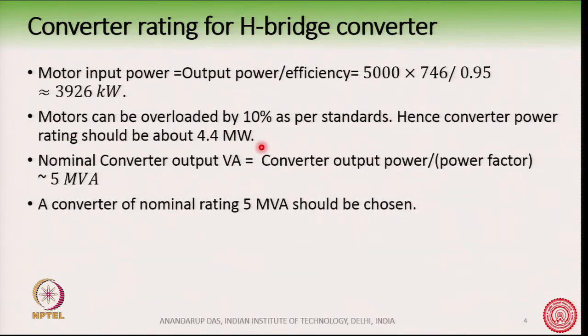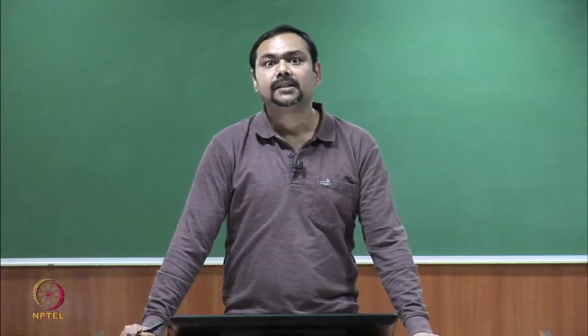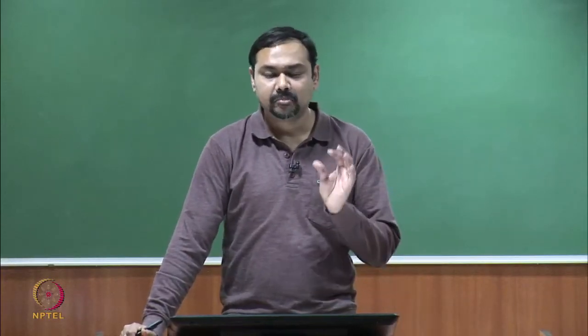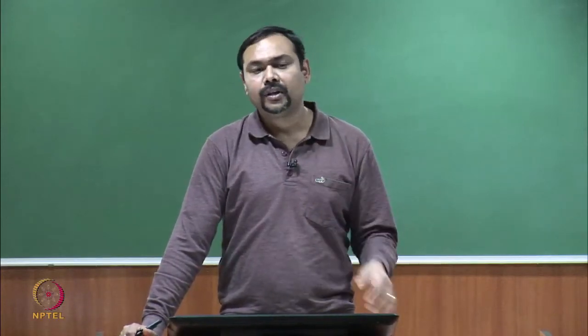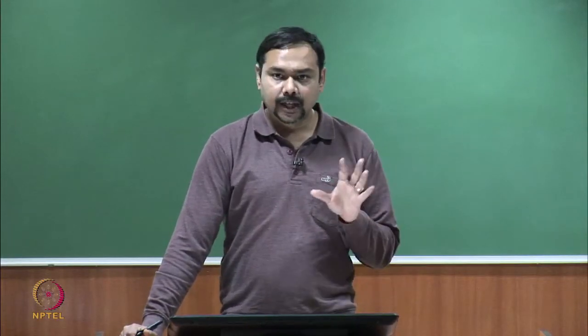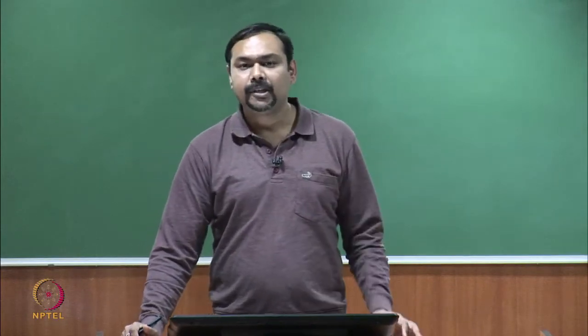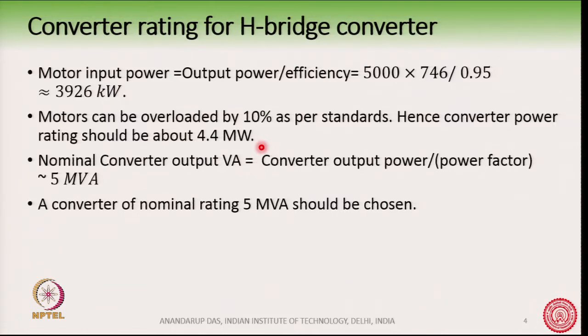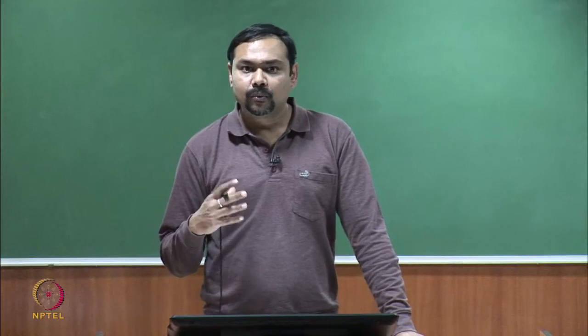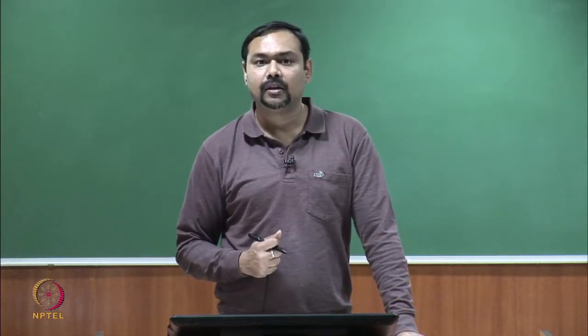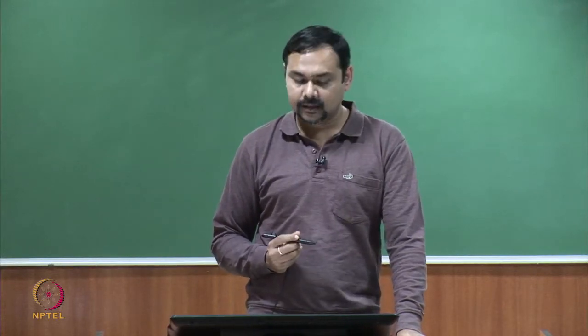When you say overload, another question that may come up is, for how long a duration of overload? Is this 10% overload for 1 minute, or is this 10% overload for continuous operation? Generally it is not continuous, it is a short term overload rating. This will vary from application to application, but we are not going into so much detail of the direct application, and we are doing a simplistic analysis here. I told you we cannot cover such a design in such a short span of time. It will require different types of analysis, and also what the worst case conditions are that this design has to withstand. All these factors have to be taken care of.